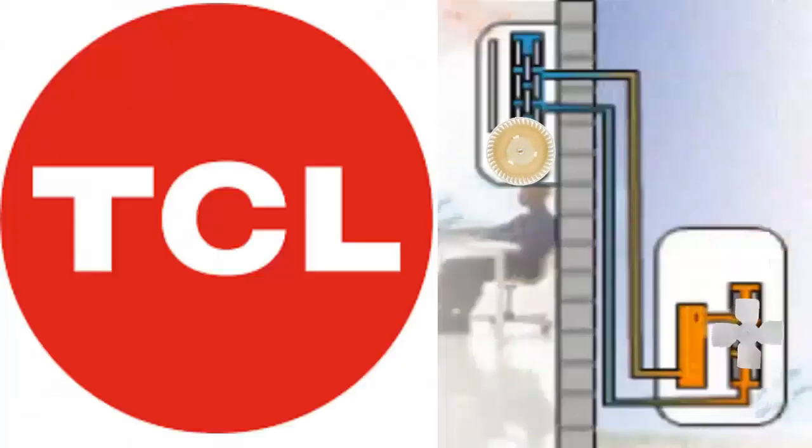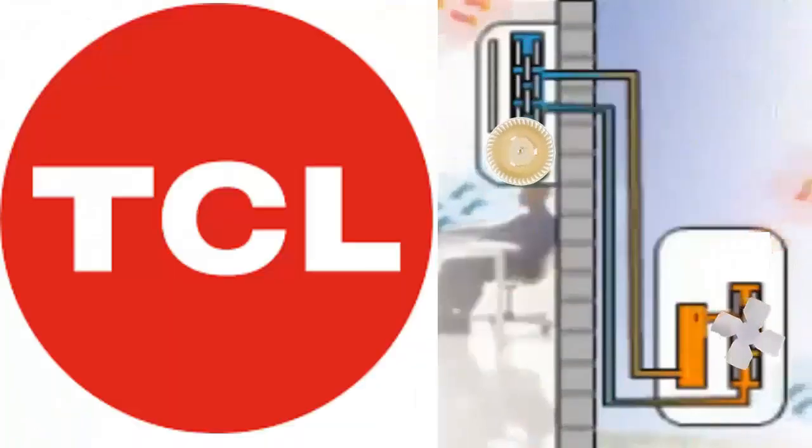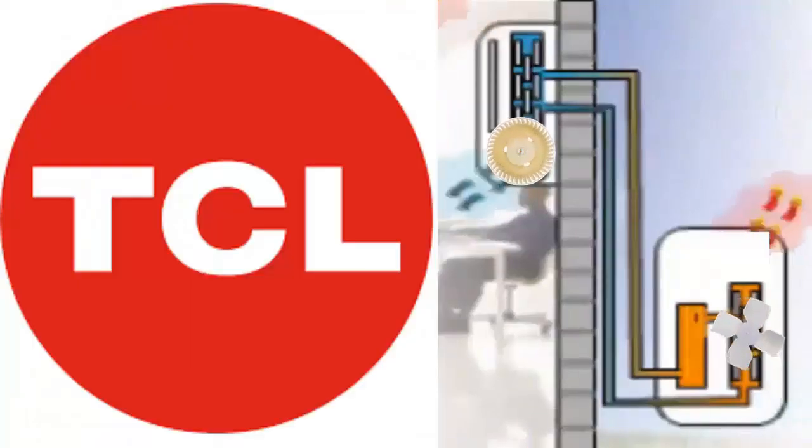The error E1 code in TCL air conditioners is related to problems with a temperature sensor located in the indoor unit of the equipment. In this case, we are specifically talking about the room temperature sensor, responsible for measuring the air temperature of the room that the indoor unit's fan sucks in, to average the temperature of the entire room.